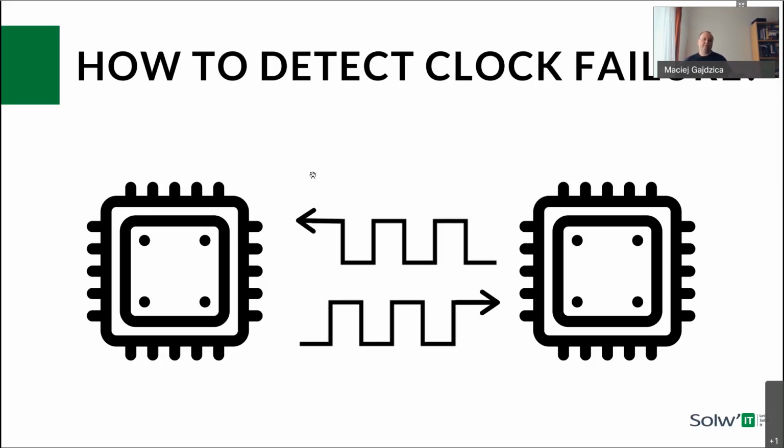Maybe our device is counting time correctly, and we received a malformed signal, so we suspect that the second processor has a damaged clock. The other possibility is that the signal we are receiving is correct, but our device has a problem with its clock. And we don't need to investigate further which one is right and which one is not. The conclusion is that we have an error in our system, so we should take proper action.